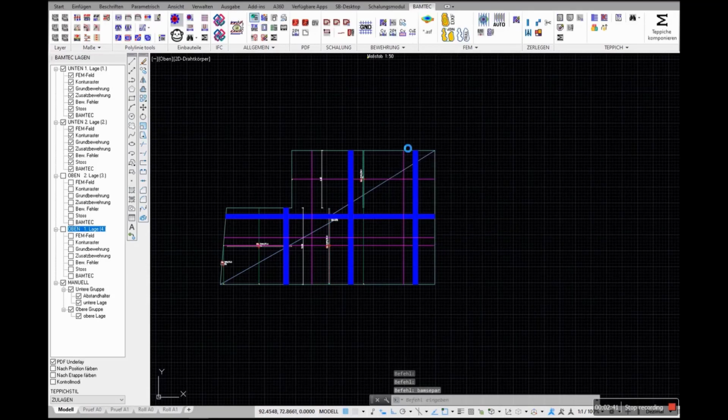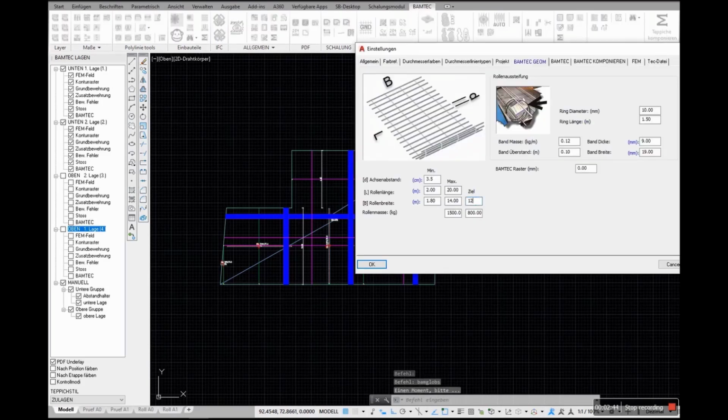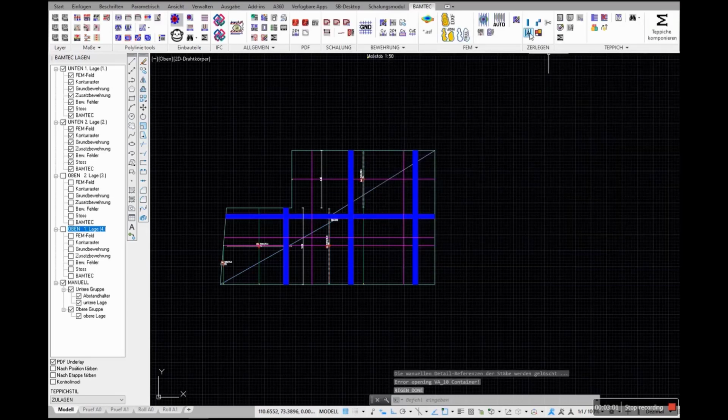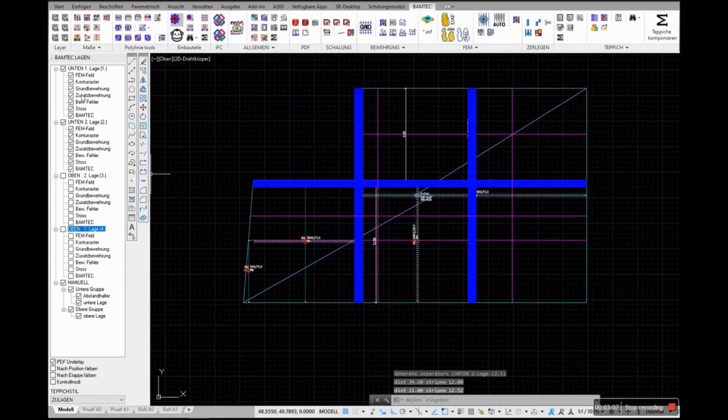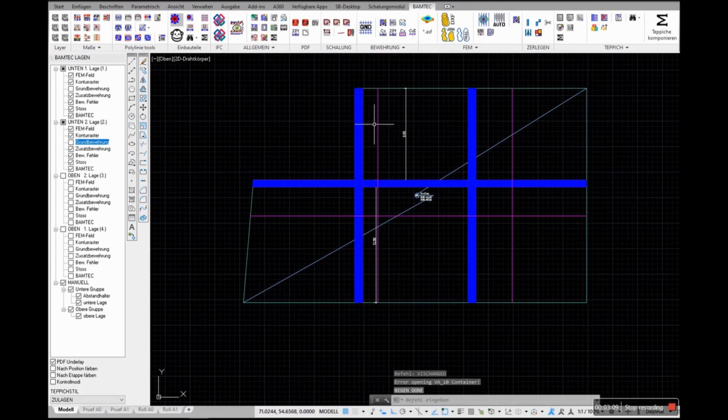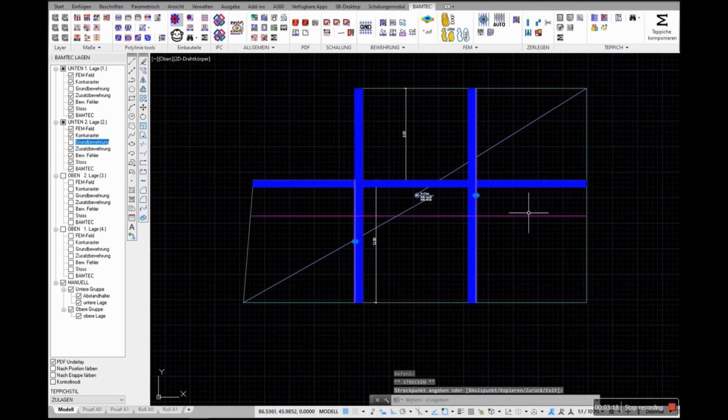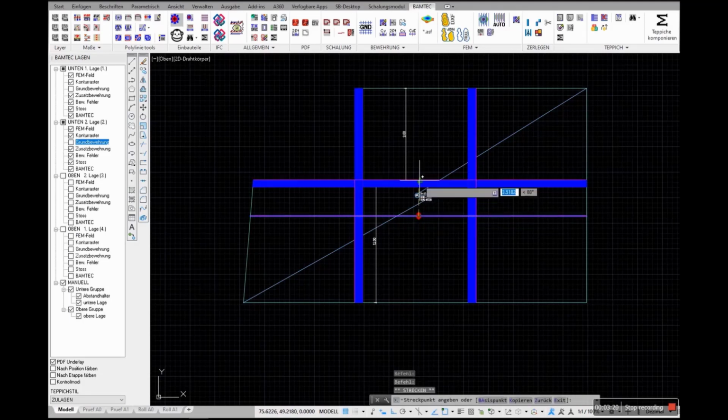So what do we do? In the project settings we can change the distances. We set the bar length to 12 meters and say the rollout length should be 14 or 15 meters actually in that case. And under these parameters, we're going to get a new suggestion in the program. The old suggestion is deleted, and here we go. This looks quite nice. We have the joints where we want them, and we can manually shift them. The joints and the cuts.